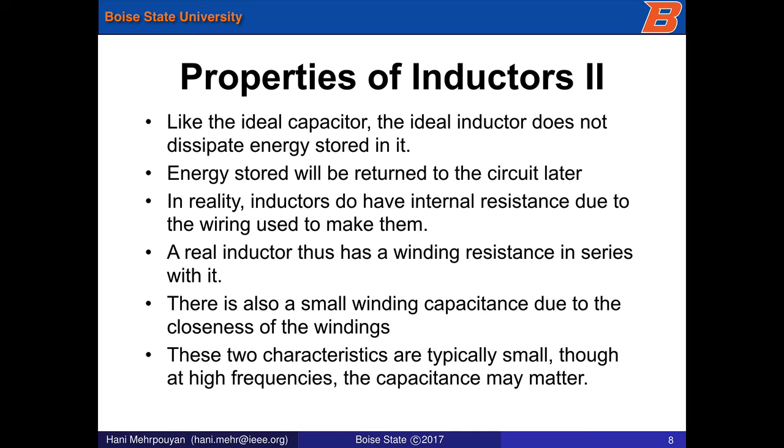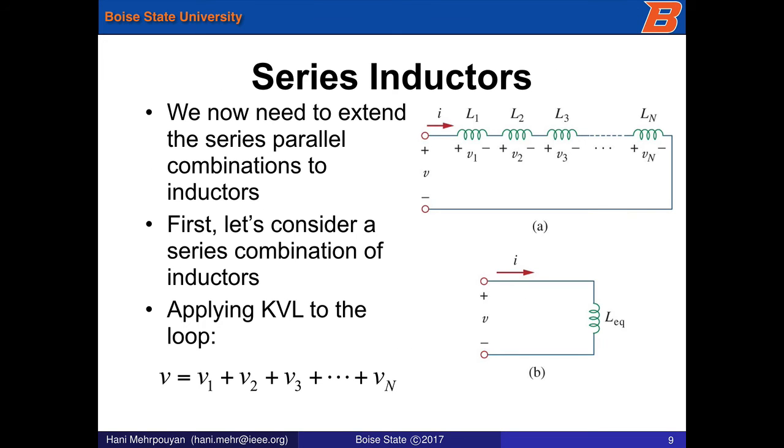You may ask, where is the stored energy for an inductor? The stored energy is in the electromagnetic field that is built around the inductor. That's where the stored energy is. And when you try to change the current inside the inductor very quickly, you're going against that electromagnetic stored energy, or magnetic energy that is stored there. And that magnetic energy will actually oppose the changes that you're trying to apply.